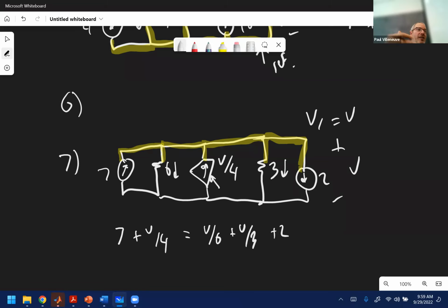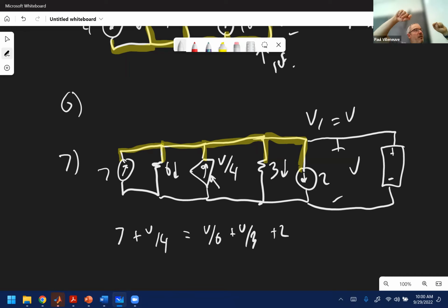So the focus is understanding what you are looking at. If you're looking at plus to minus V and you're not exactly sure what it is, go ahead and draw a little multimeter and say, here's my plus terminal, here's my minus terminal. What voltage am I measuring? So bring your probes away from just looking at that current source, and bring your probes all the way to the end of where another node or another impedance device comes into effect. And then sometimes it reveals that it's just the same voltage.